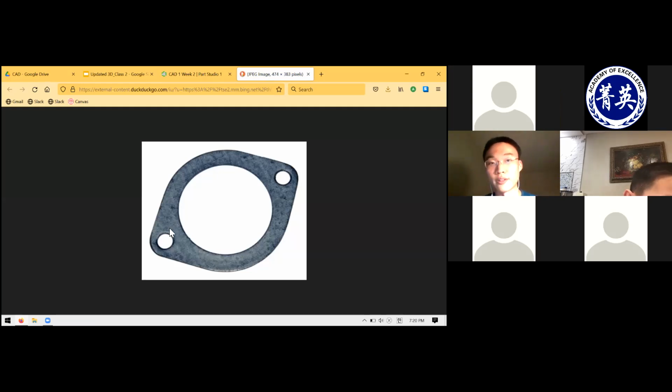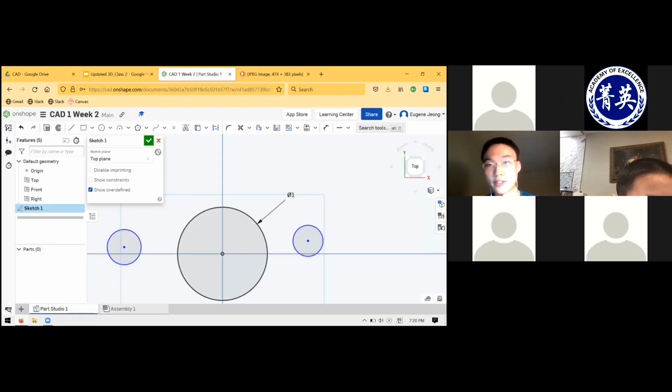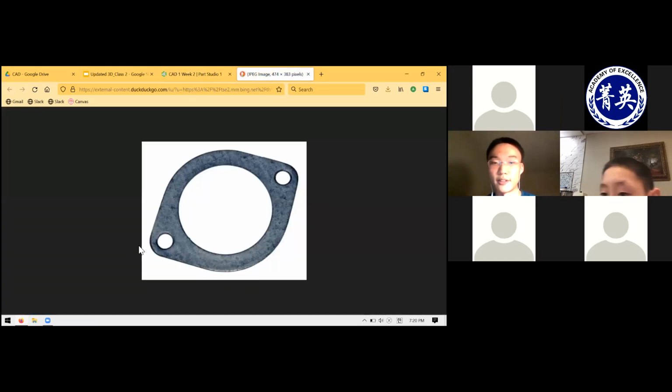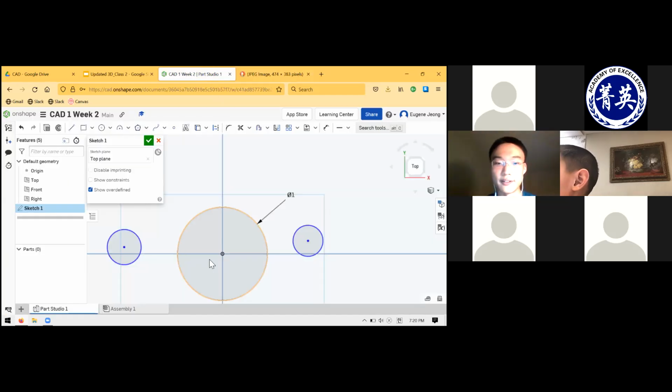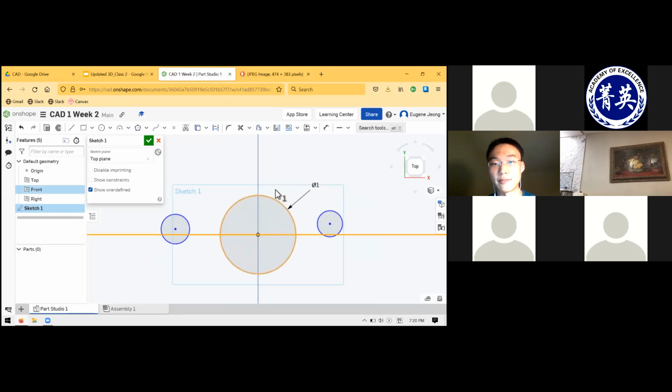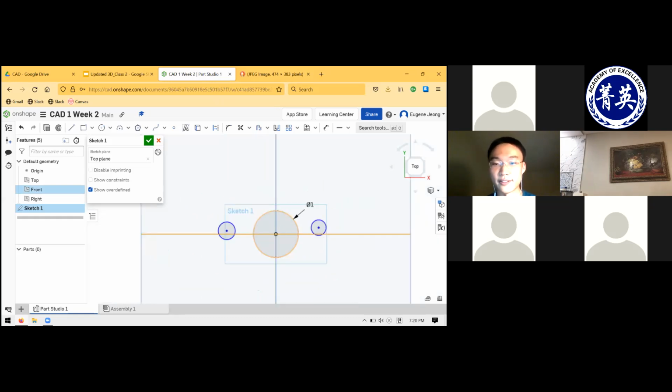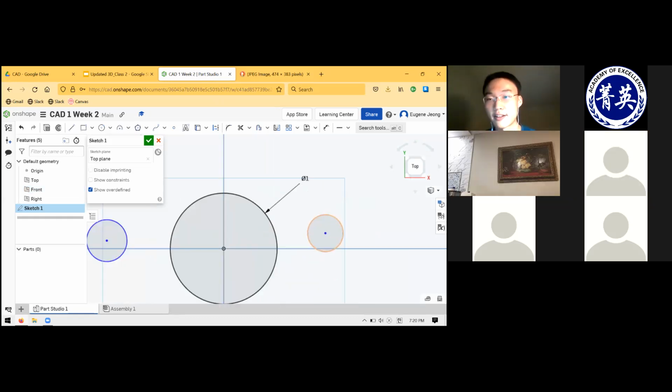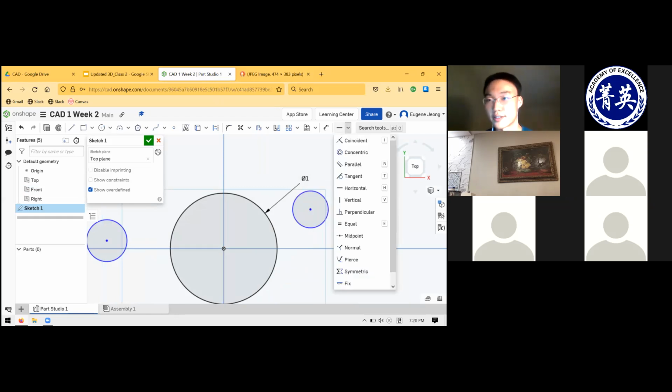Anyway, my goal here is to, what was I saying? Create these other holes. And just for the sake of simplicity, I'll assume all of these 3 holes are collinear. Their centers lie on a line. And I'll conveniently just choose that line to be this horizontal axis. So if I just happen to naively create my circles wherever, like I did just now, it'll be completely unconstrained. But the way that I can add a few constraints is by use of my relations.